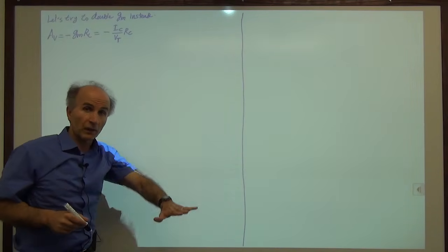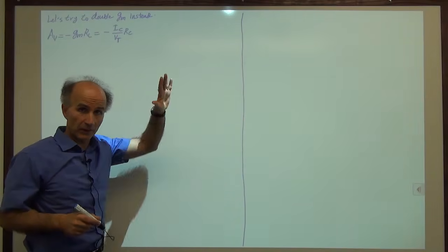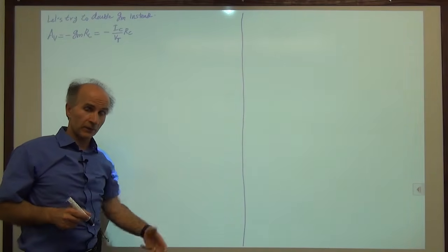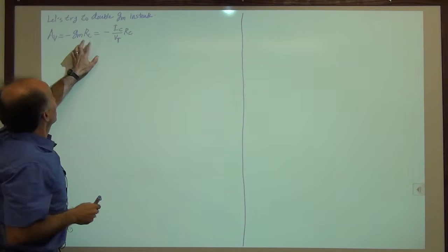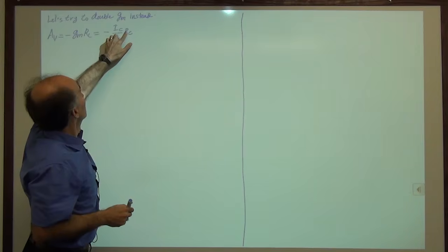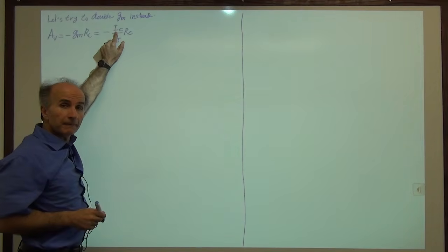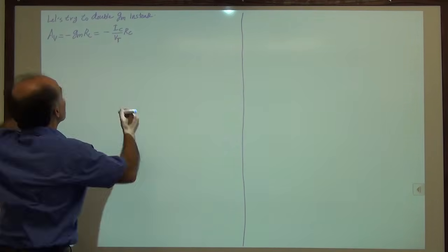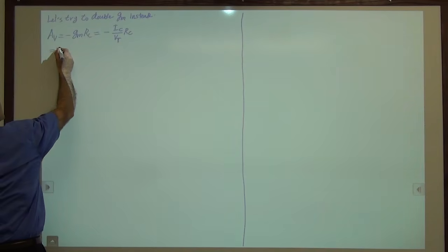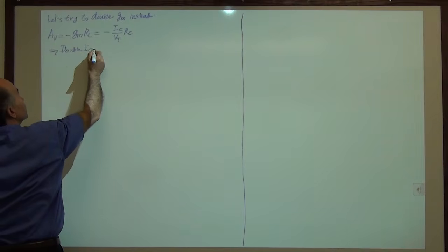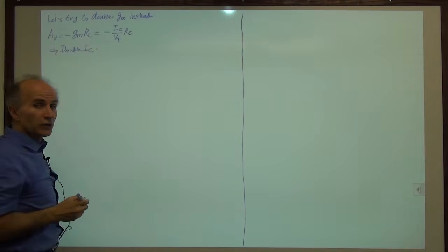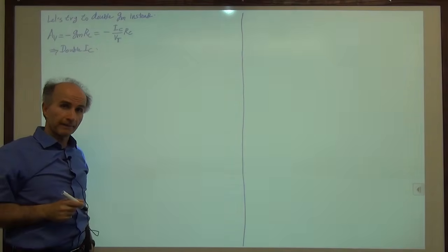The collector bias voltage, without any signals, falls so much the device goes into saturation. Okay, so to double GM, what can I do? I have to double IC. There's no other way. So double IC. The question is, is this better?